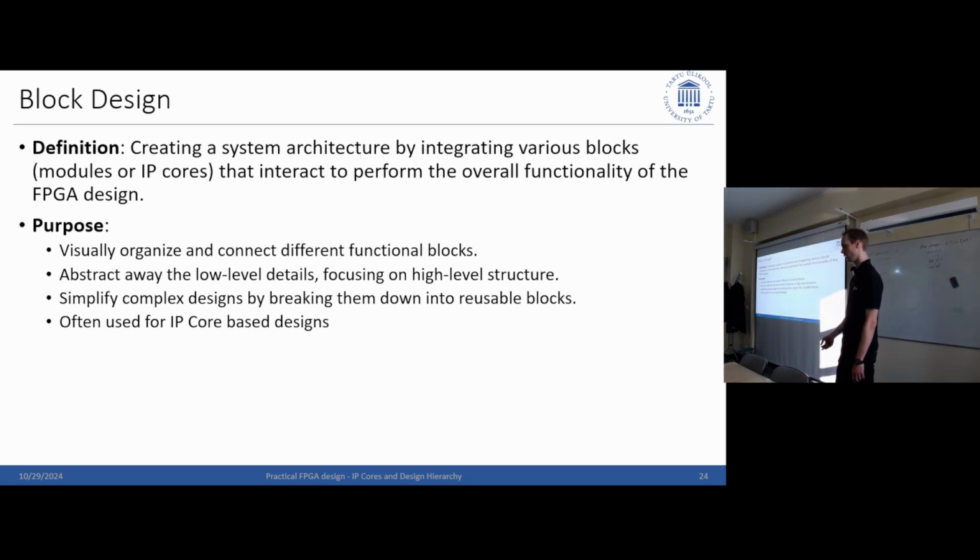Yes, for example, especially for IP cores like memory blocks and so on, these test benches allow you to emulate the memory. Because you have your IP core which interfaces with the physical memory, but if you want to simulate that, you would have to write that memory.